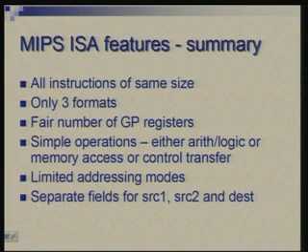The set of operations is fairly simple, and the thing to be noted here is that each instruction tries to do just one thing. When I say that, what I mean is that an instruction will either do an arithmetic operation or a logical operation, or do comparison, or do memory access, or it will do a control flow, okay, a branch or a jump. There is no instruction which tries to do more than one of these things.